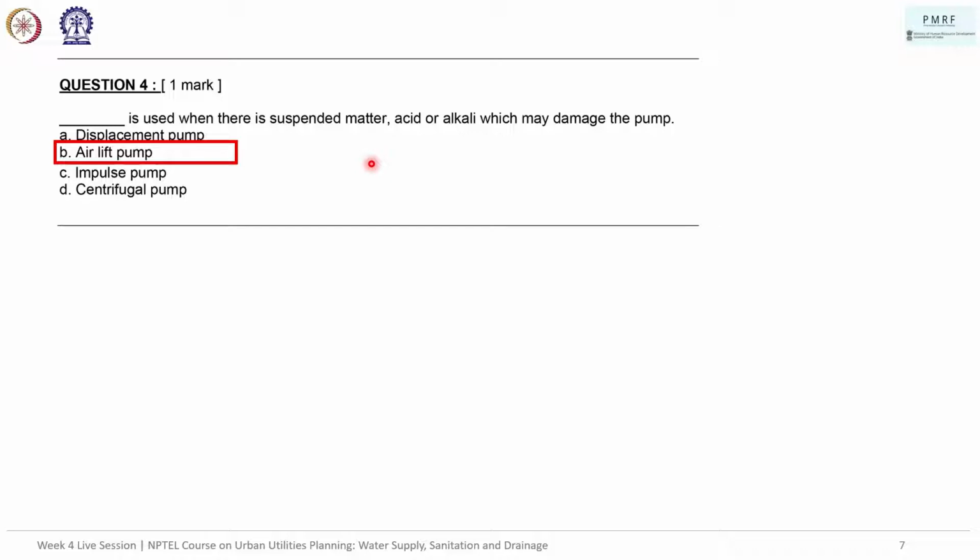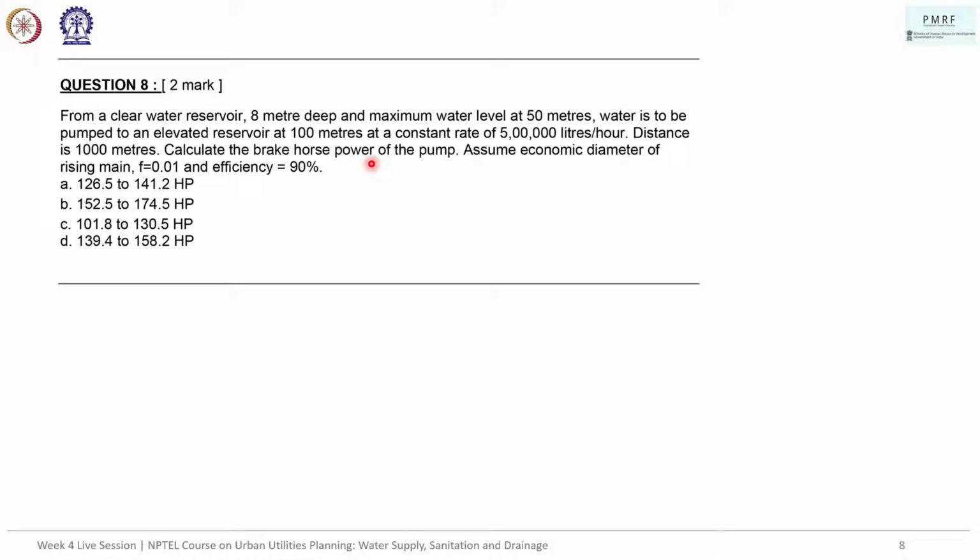The issue with sewage is that its density is going to be so high that airlift is probably not going to be the best option. However, without specifications on the density, assuming that we are looking only at water supply, then airlift pump is the standard way to go. So I hope that clears this.